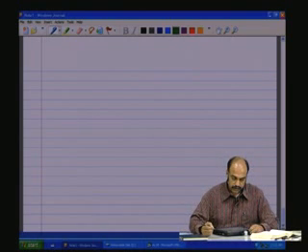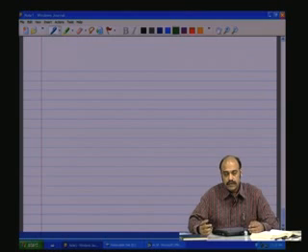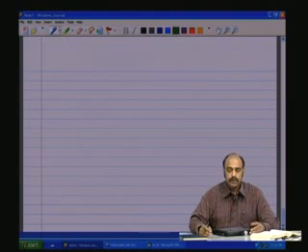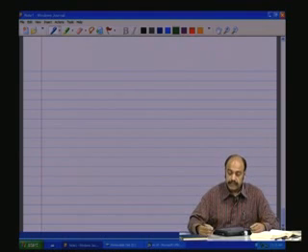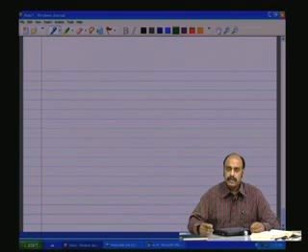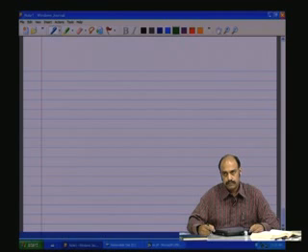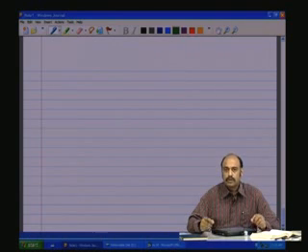Now there is one important thing that you should know. We saw that there are machines with different number of poles. You have the 2-pole machine, the 4-pole machine, 6-pole machine, 8-pole machine, 20-pole machine, so on, for different applications. What is the maximum synchronous speed that one can achieve for a given frequency source? That is at 2 poles.